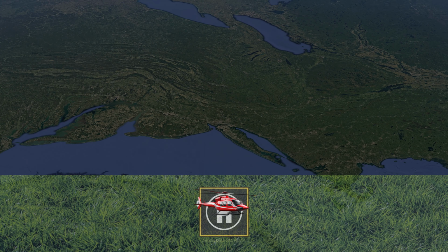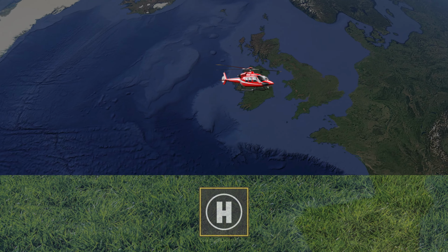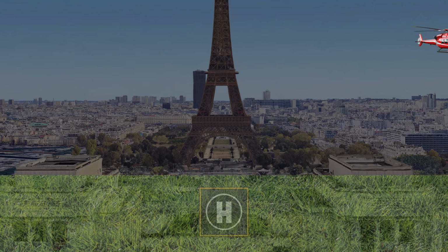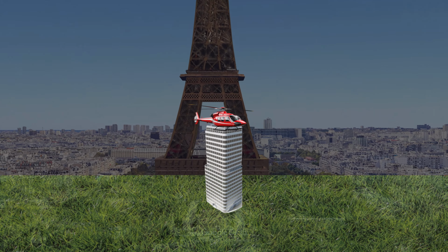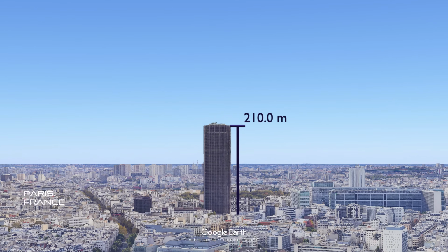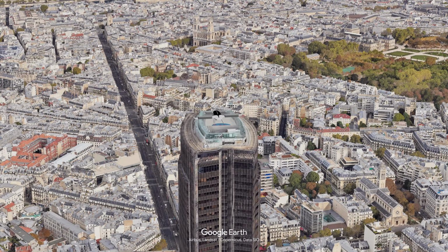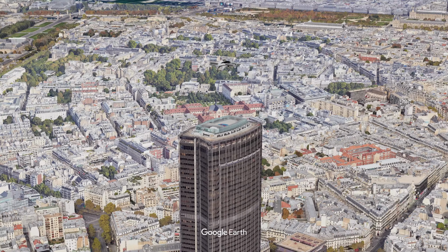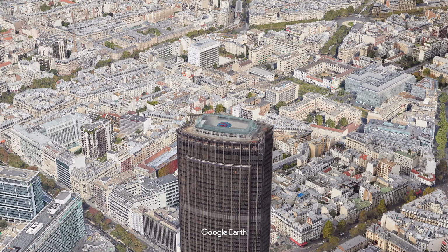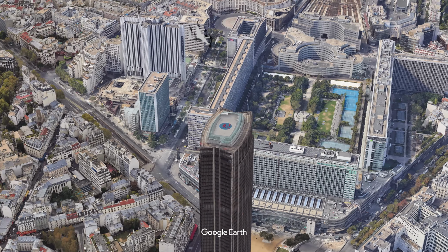The conventional ground takeoff is similar to how helicopters operate. This involves takeoff from a ground-based helipad or, in some cases, a short runway. The elevated conventional takeoff is a regular takeoff from an elevated area higher than 3 meters, such as a rooftop. And lastly, the vertical takeoff. In this method, the aircraft ascends vertically before transitioning to horizontal flight. This is a key feature for urban air mobility, as it allows aircraft to operate efficiently in tight spaces, with minimal runway requirements.